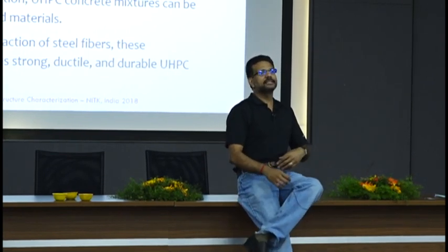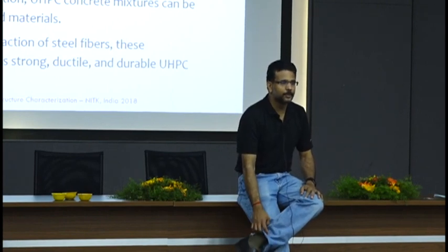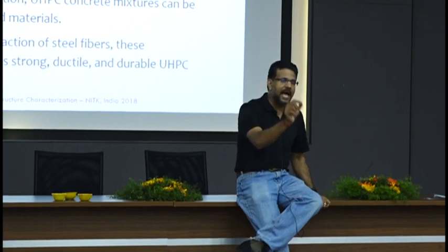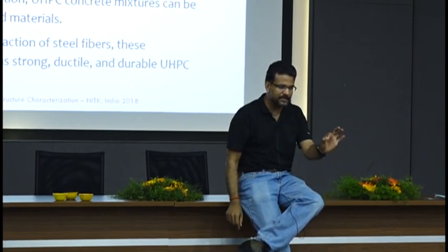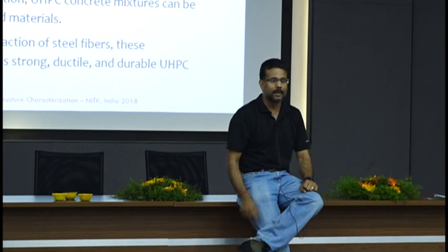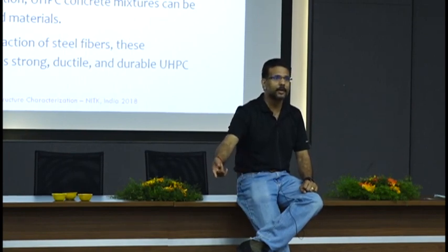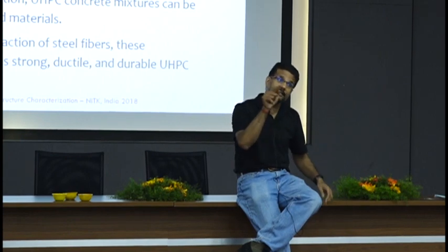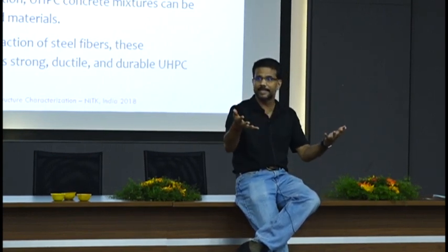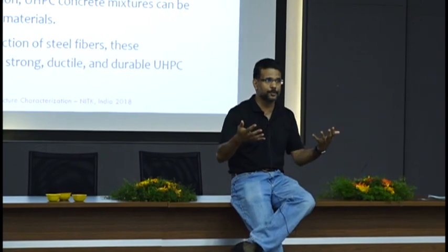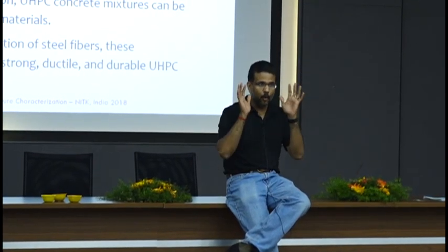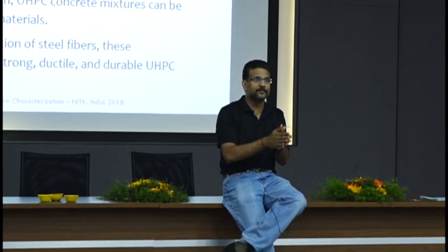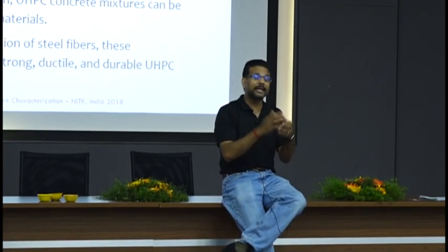So none of these are exact sciences. People will fool you with it. How much of CH gets converted to CSH, is that exact? If you measure it at a certain time, you get a certain number. You measure it after 10 more days, you get a different number. That's a function of how much your cement actually is hydrated. I talked about this yesterday, right? It's a competition issue. The only way you can kill it is by using silica fume, large amounts of silica fume, because silica fume will immediately react. But even then,